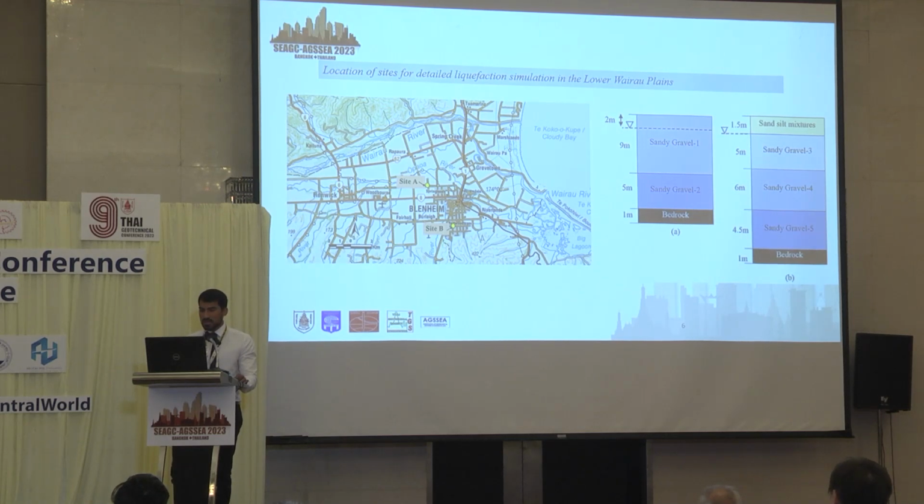So for site A, I divided it into two gravelly soils. This was mainly based on the relative density difference. As we go down, the relative density was increasing. So that was the differentiation point which was selected to have the gravel 1 and gravel 2. And it was 15 meters of depth for simulation.